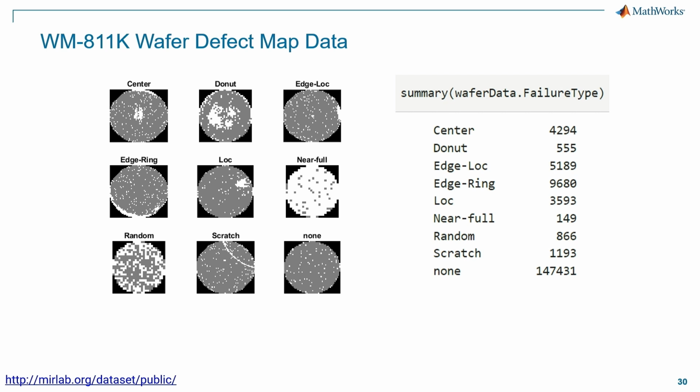They actually contain 811,000 wafer map images, including 172,000 labeled images. So roughly 20% of the data is labeled. Each image has only 3 pixel values: 0 means background, 1 means a correctly behaving die, and the value 2 means there are defects.